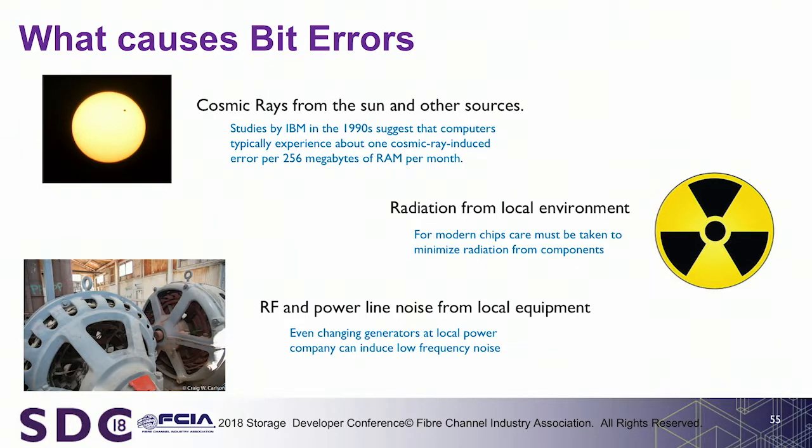And then there's RF noise and power noise from local equipment, or non-local equipment, because I did hear a story recently. Somebody told me about a data center that was crashing frequently at the same time every day. It took them a couple weeks to figure out that the reason it was crashing was because at that time the local power company was switching its generators, and that generator switch would cause a low frequency noise to be put out in the power lines, which was getting up into the electronics and causing some havoc.